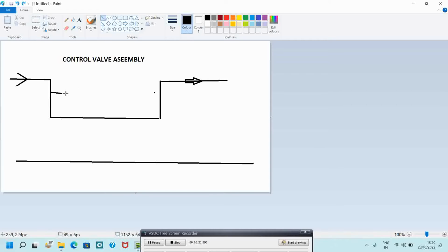So we have to draw the bypass line from here, and one valve is there. I can mention the valve symbol like this. Just understand this, this will be the valve symbol. This will be the bypass line, and the bypass line's globe valve should be near this T area. Not center. It should be as near as possible, maybe within 100 or 200 mm. It will be better. This is as per the procedure.